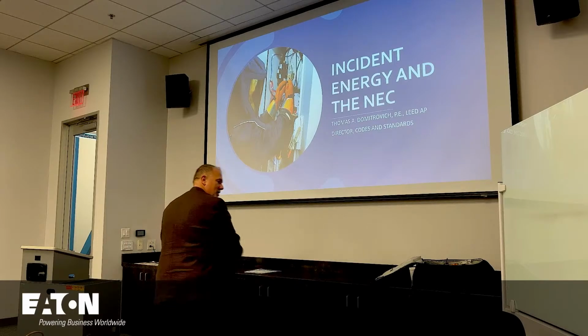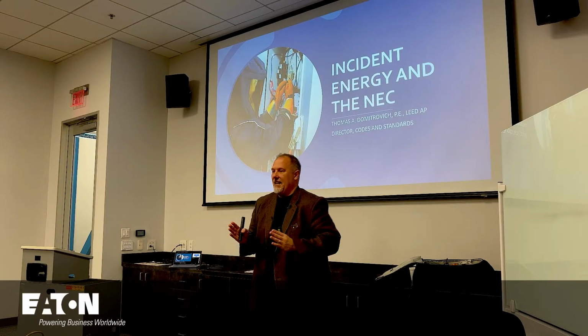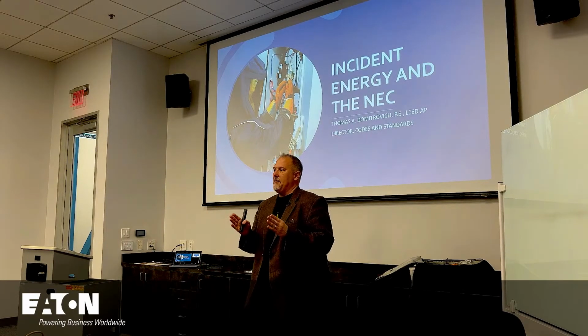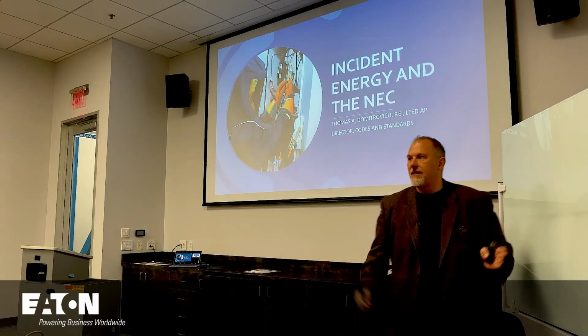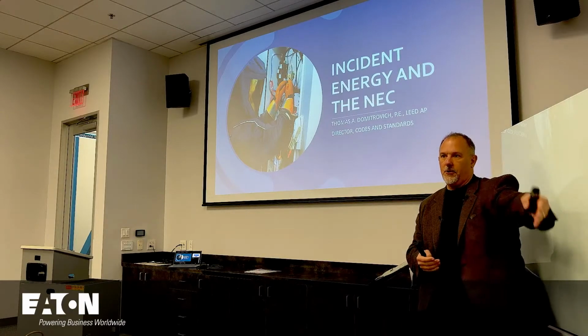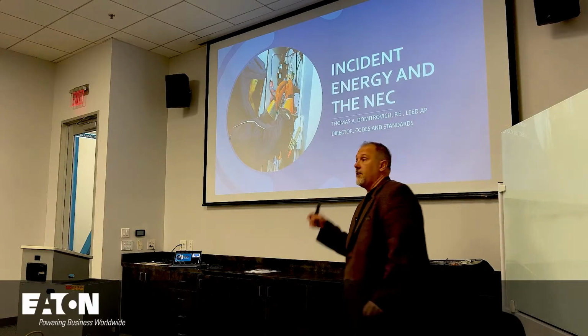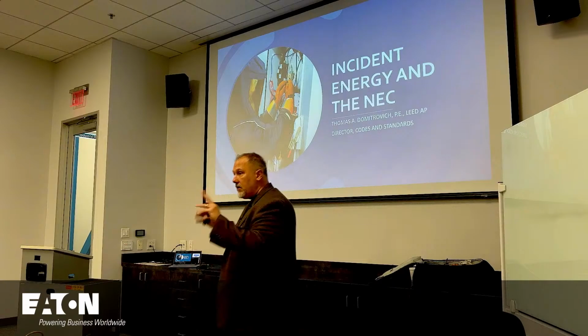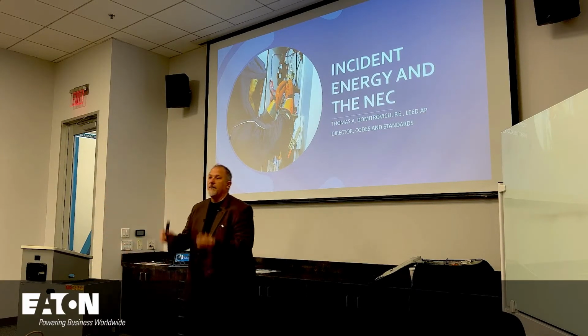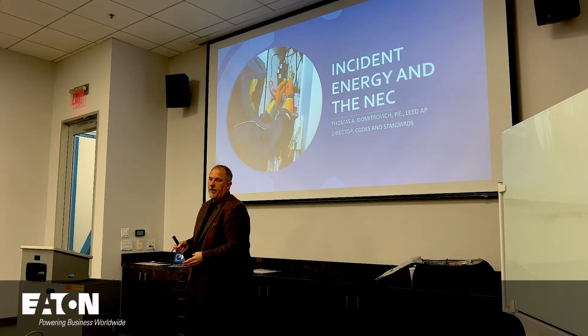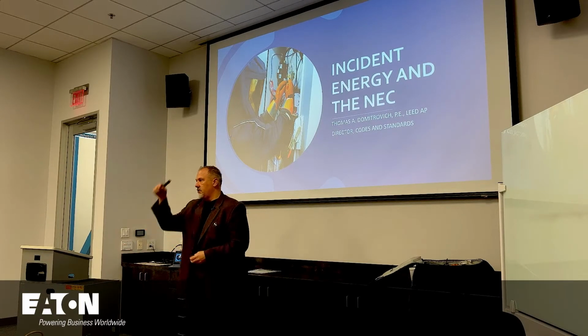So at 0 current, I'm at the instantaneous on a 600 amp breaker. When I put in a 4,000 amp breaker, I go this way in my instantaneous. My instantaneous pickup goes larger. So what the industry started to experience when they made those 3 critical changes was what they called burn downs of service entrance equipment. Arc flash events on service entrance equipment.